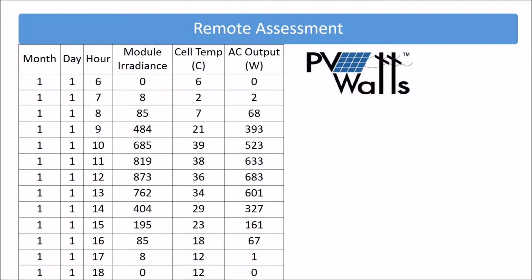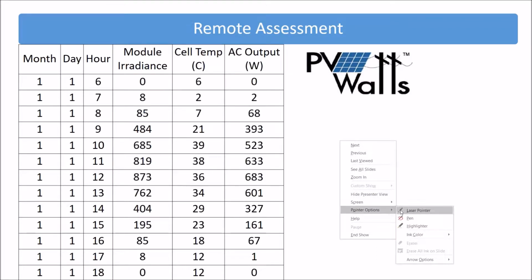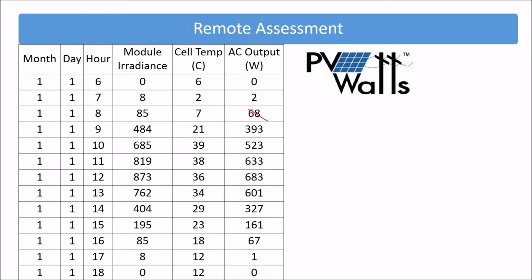And so it might be that the house next to you, or the tree that doesn't go up above the roof but is level with your solar array, at those times it may be that the sun is so low in the sky that we just simply ignore these tail end numbers that are a little bit small. Even if your array has no shade on it, it could be that the shadows have gotten so long that power isn't really ever going to make it out of the system.